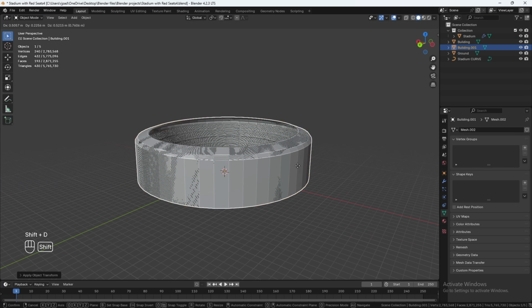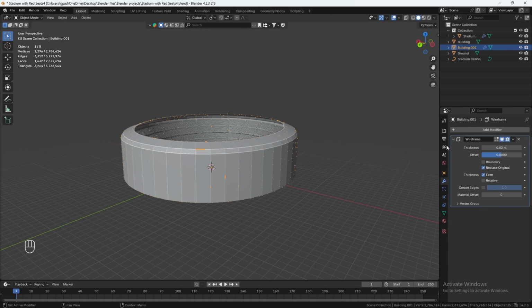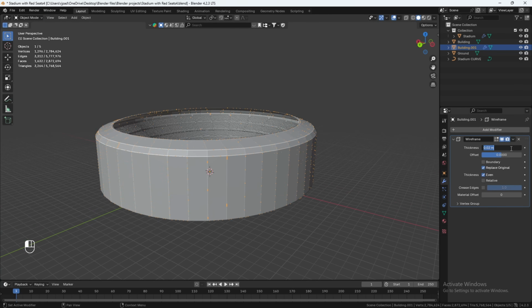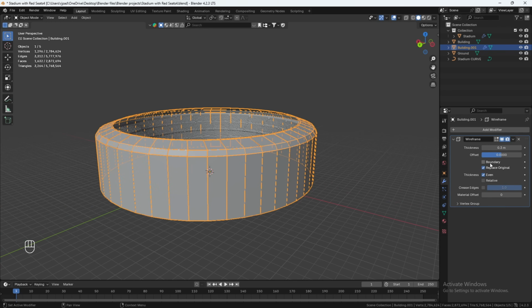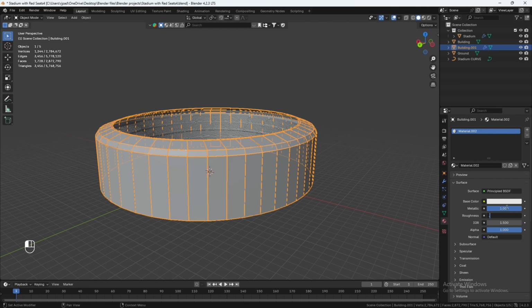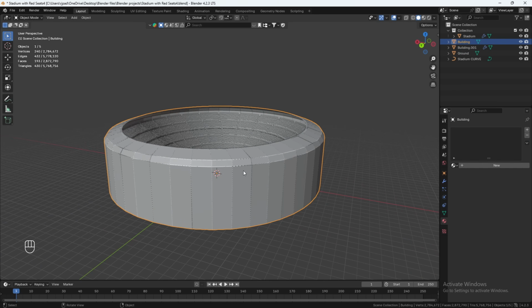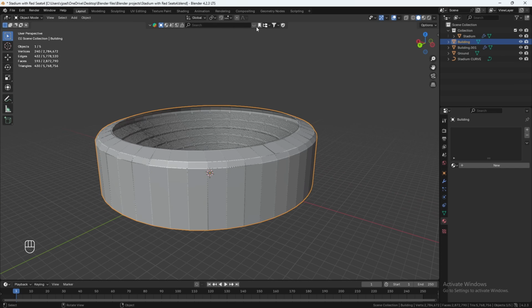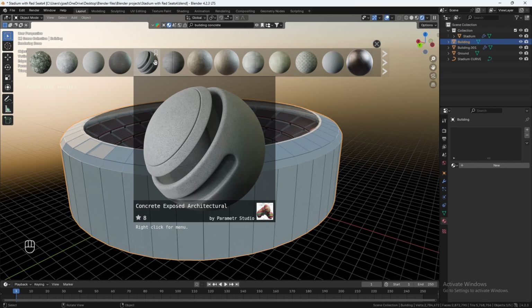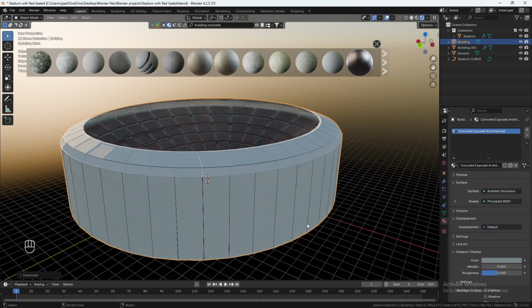And then let's do Shift T to duplicate the building, escape to set it back in place, add a wireframe modifier. The wireframe is going to be 0.3. Checkmark boundaries, give it a material, metallic 0.1, and we'll also give a material to the base building here. So I'll give it a concrete material. I'll go to the material tab here on Blender Kit. I'll search for building concrete. Let's go into render mode. I'll use this one, click and drag it onto our building, our base building here.